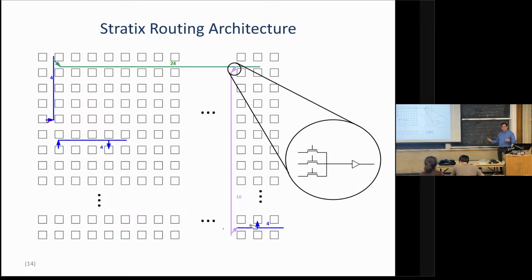So in the next generation, we doubled it. But to double it was challenging, to find enough high-level metal. But it was doable. To quadruple it and so on probably isn't doable, not without adding a bunch more metal layers. You can add more metal layers in the manufacturing process, but it makes your chip more expensive.